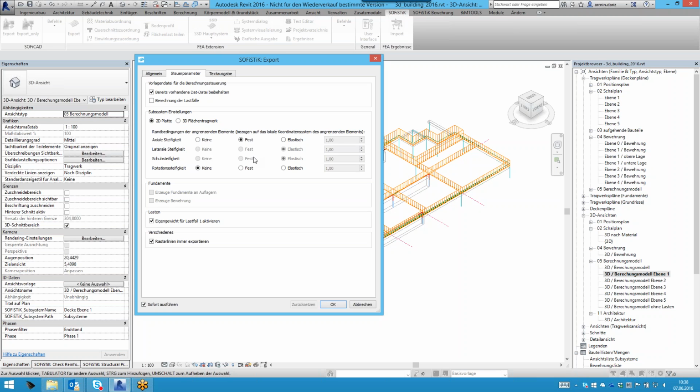And you create a 2D slab with vertical supports where on the support lines or points, as walls or columns, you don't have any deflection. And also here, when we talk about slabs which are supported by single columns, normally you get some singularity on that point, and you get worse bending moments and a lot of shear problems if you use fixed support conditions.